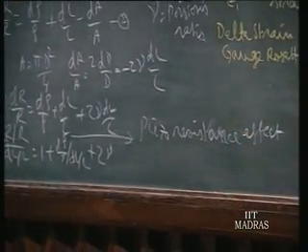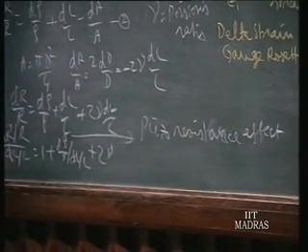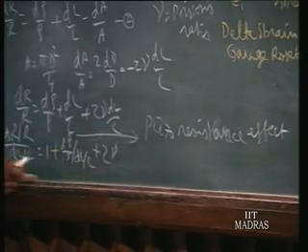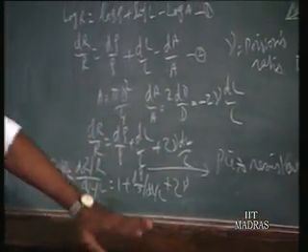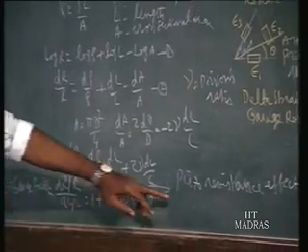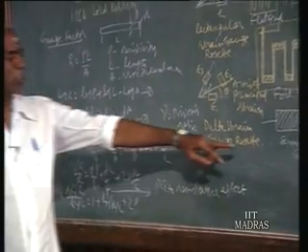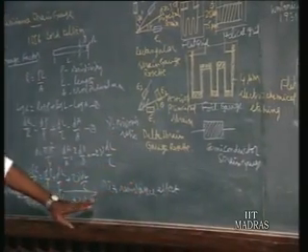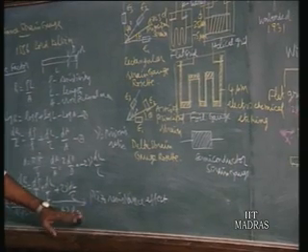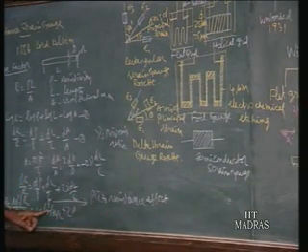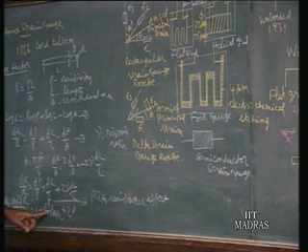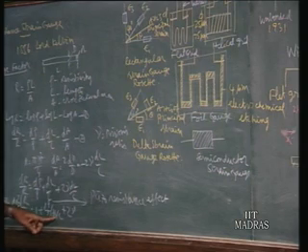For a metallic wire, generally the gauge factor is around 2. So you find here 1.6, and 0.4 comes from this piezo-resistance effect for metallic wires. Whereas for semiconductor strain gauges, the gauge factor is around say 100, 120, whatever it is, a very large number, and that is mainly due to the piezo-resistance effect, d rho by rho over dL by L. That is, the resistivity of the material itself changes when there is a strain in the semiconductor material.